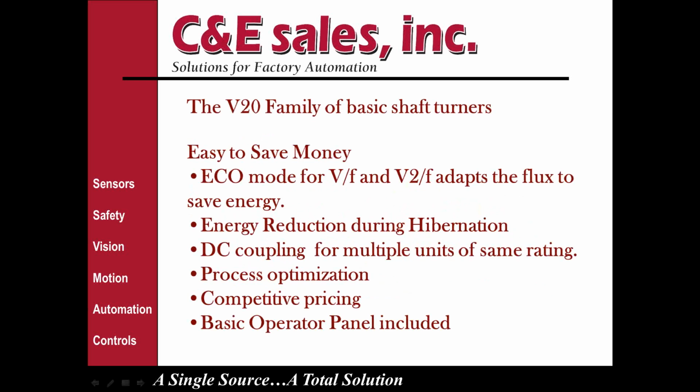A nice feature of the eco mode is that if your system varies from running to an idle state, it constantly monitors the flux, and if you're at zero speed, it's going to drop off the flux, which saves you a considerable amount of energy in applications that start and stop frequently. And there's also a hibernation mode that falls in with that, so that it drops the voltage to the motor when it's not in use.